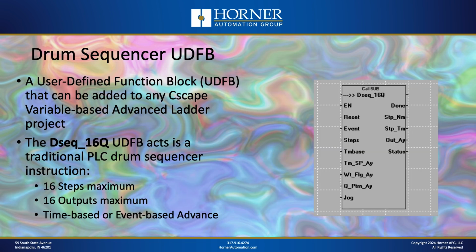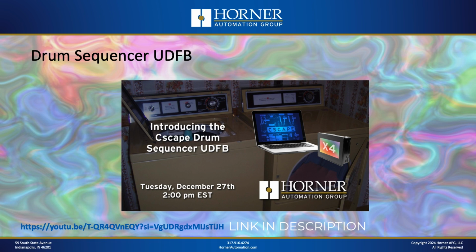So that's why we created this drum sequencer user-defined function block. And again, I'm not going to go into much detail here because we have a very detailed video that will give you all you need to know about the drum sequencer. But our drum sequencer is quite capable. It can handle up to 16 steps. It can control up to 16 outputs. It can advance from step to step based on time. It can advance from step to step based on an event, like an input changing state, for instance. Or it could be that both have to happen before you move from one step to the next. So very capable UDFB there, and here is the title and the thumbnail and the link to this video.